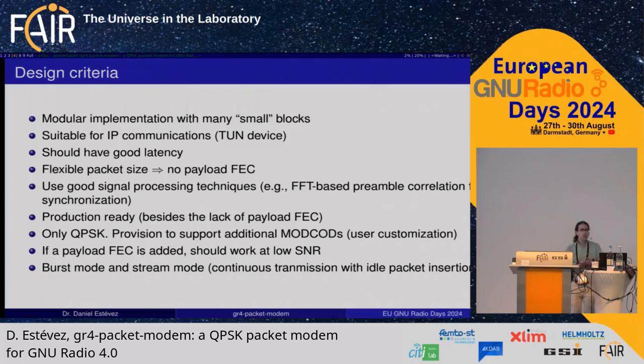It should use good signal processing techniques. We're having these packets, they have a preamble, so we should use FFT to detect the packets and synchronize, rather than saying, oh, but I have my Costas loop, and I need to have a long training sequence because of the bandwidth, and it doesn't lock.